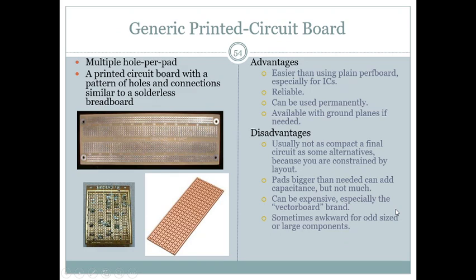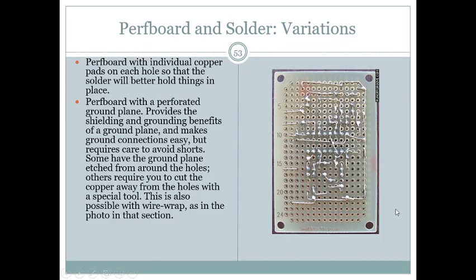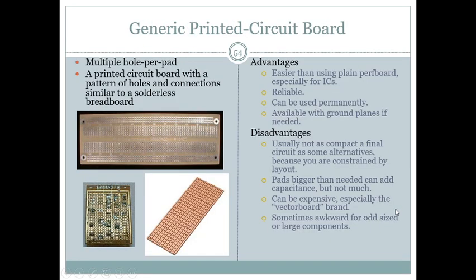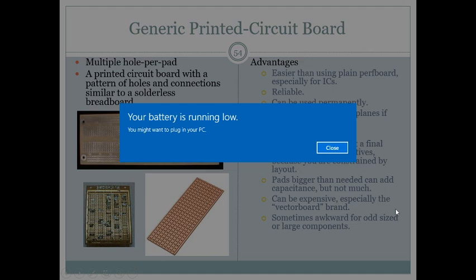Then general printed circuit boards. We call these strip boards. This is the dot board. This is the strip board. They are generic. They have certain copper strips already laid. So in this case, if you want to make connections, the strips are already there. But don't forget that the strip from one end to the other end is connected. So if you don't want that much distance, you will have to damage the strip in between, and then you get the connection you want.